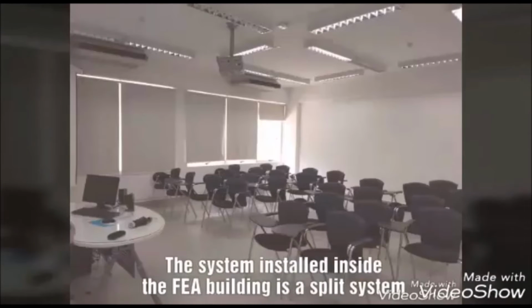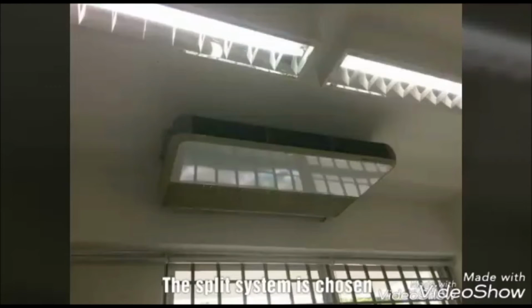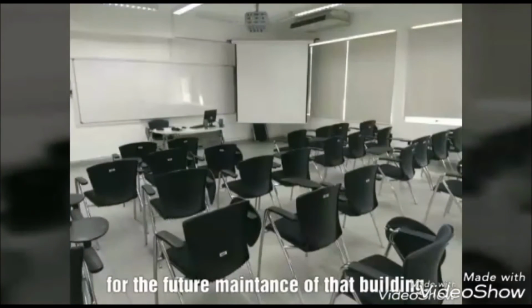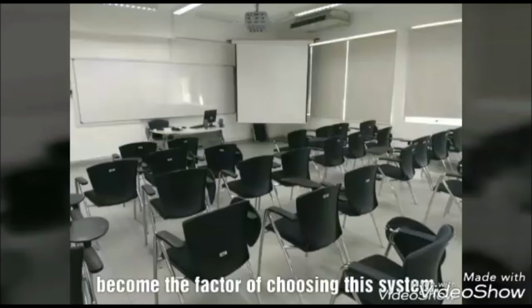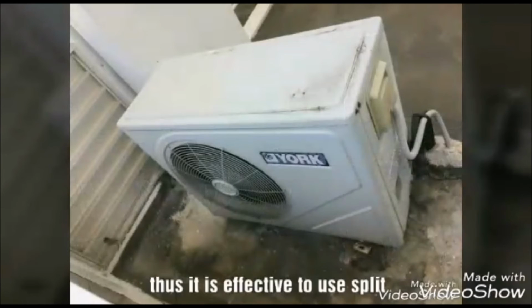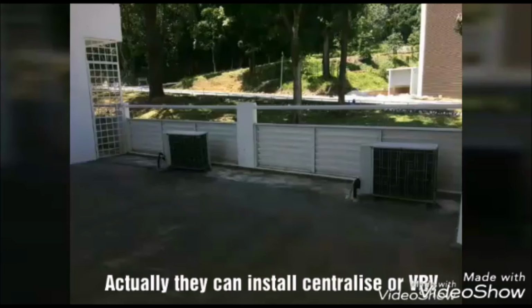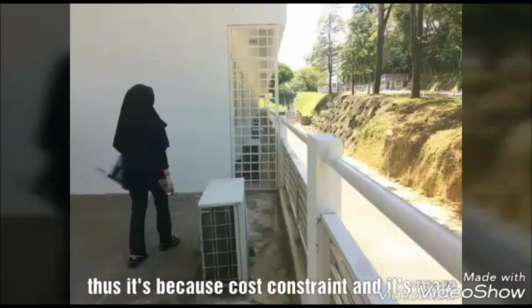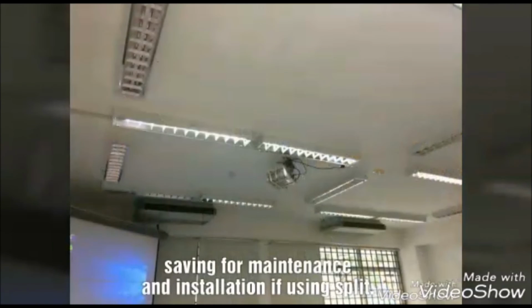Installed inside the FEA building is a split system. The split system is chosen due to budget calculation, costing and also for the future maintenance of the building. The size and the volume of the room become the factors in choosing the system. The FEA tutorial room is quite small, thus it is effective to use split. Actually, they could install centralized or VRV, but the cost would be expensive. Thus, because of the cost constraint, it is more saving for maintenance and installation to use split.